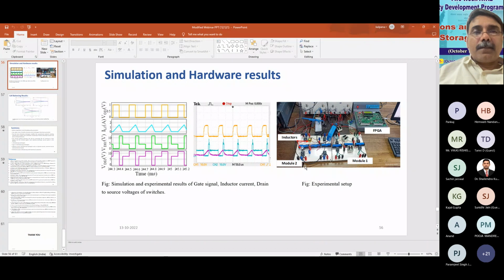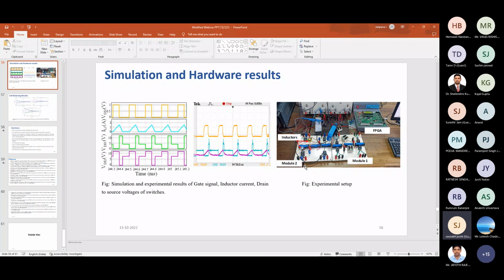Yes, this is a right question, because how are we sensing the voltage, and how do we know which cell is higher? We have to provide a sensor for each battery, and there are three different cases. The battery can be balanced in charging mode, in discharging mode, and also in standalone mode.